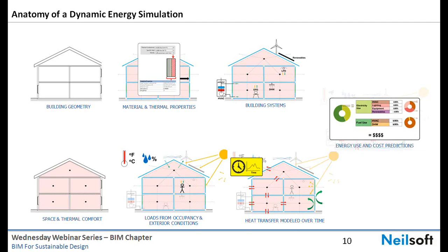Whatever building programs we use, we are capable of applying ASHRAE 90.1 standards, and we use all the standards from the different sectors and environmental conditions outside the building, heat and humidity from the people, set points or the target temperatures of the spaces. All these data are taken from the standards of ASHRAE 90.1. Outside air temperature, relative humidity, wind speed and direction, direct and diffused solar radiation, infiltration assumptions. And after that, there is one more heat transfer model over time.